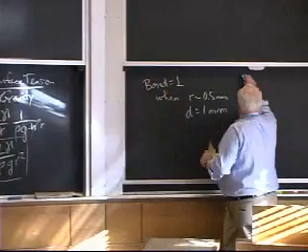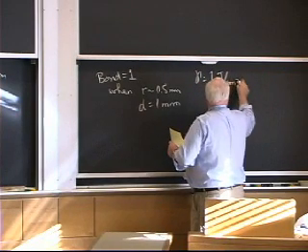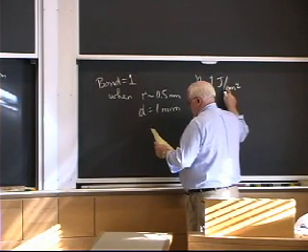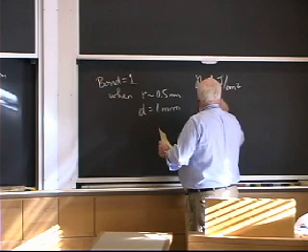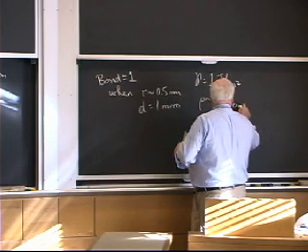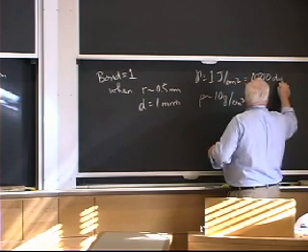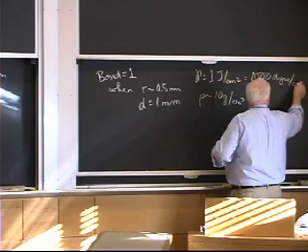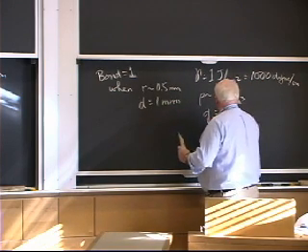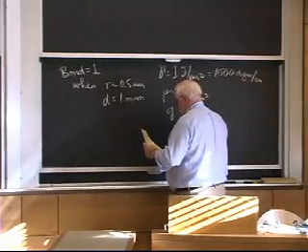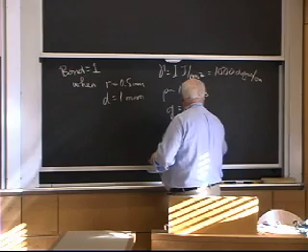So gamma is equal to 1 joule per meter squared, and rho is about 10 grams per cubic centimeter. So this is 1,000 dynes per centimeter. Gravity is 980. And if you solve that particular one, you get R is 3 millimeters rather than half a millimeter.